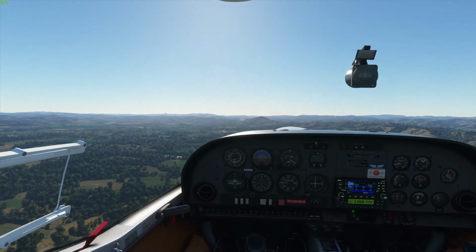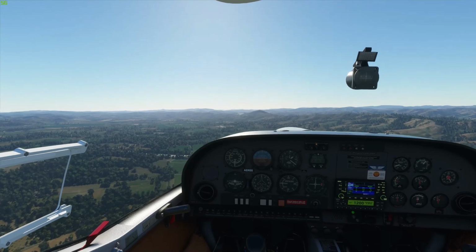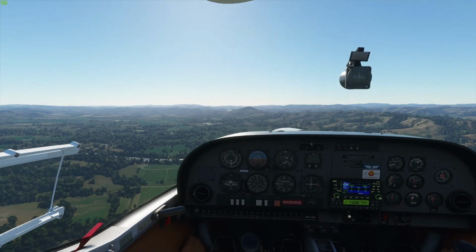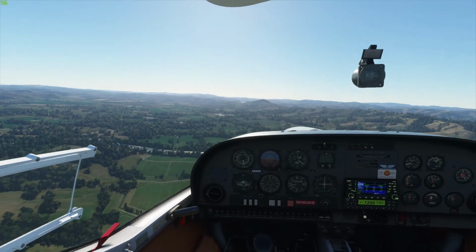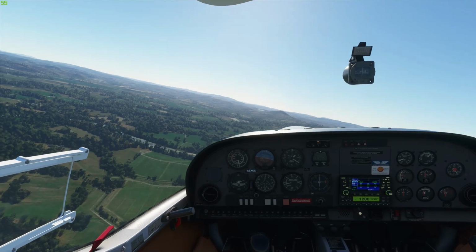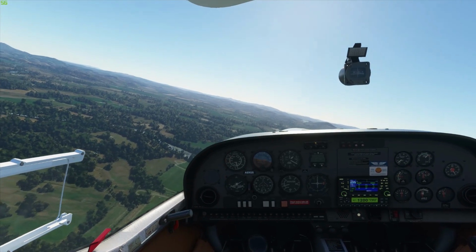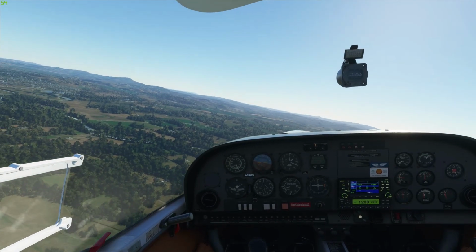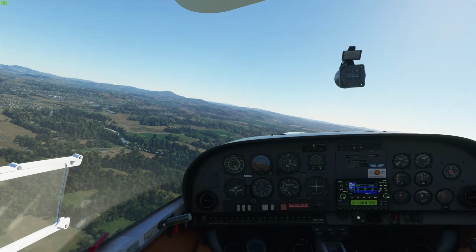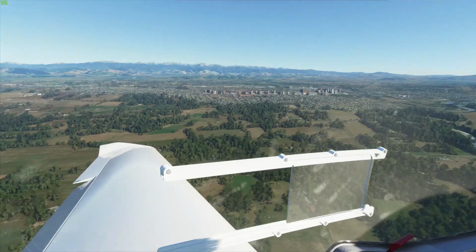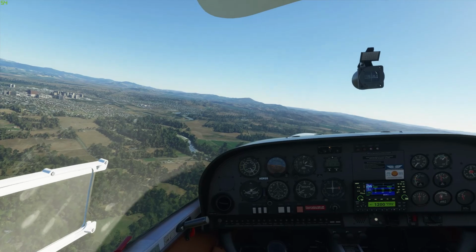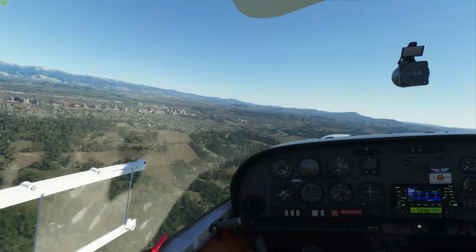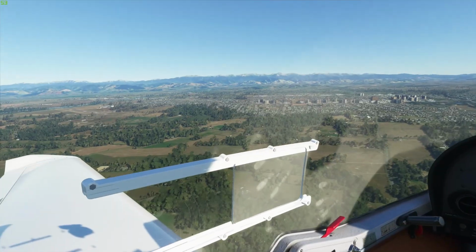Okay, so we're looking for the top of the white arc, which is there. Catch that balloon, start the turn onto base and a bit of a descent, and I'll reduce the power so that we get 70 knots. So I'm increasing the nose attitude for 70 knots and then decreasing the power and the attitude just a little bit to set up that descent, and using elevator trim, positive or nose up trim, to stabilize at the 70 knots.